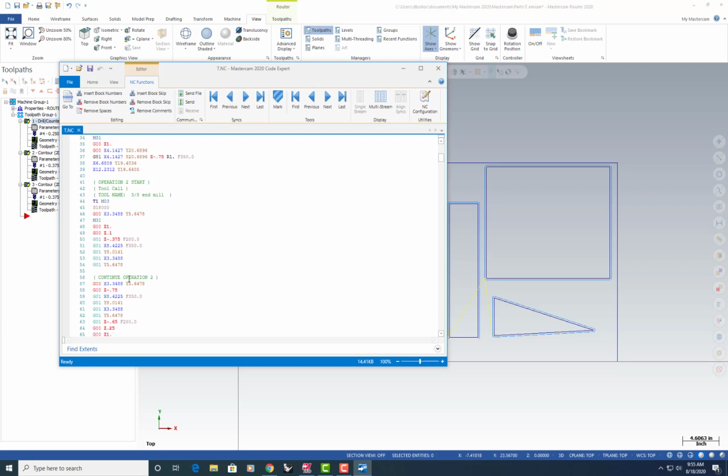Some G code is pretty simple and only a few lines, but some are hundreds of thousands of lines long, so it's hard to troubleshoot it all. But I usually look at the first 20 or so lines and see if that seems like reasonable numbers.